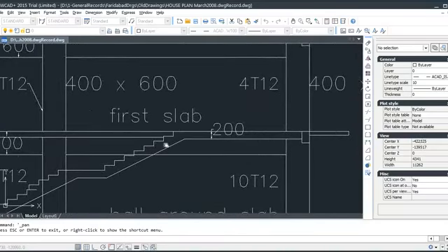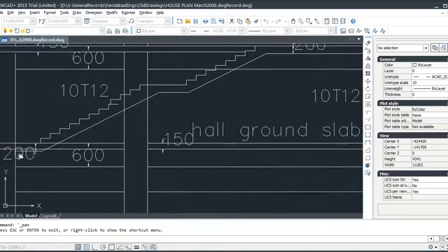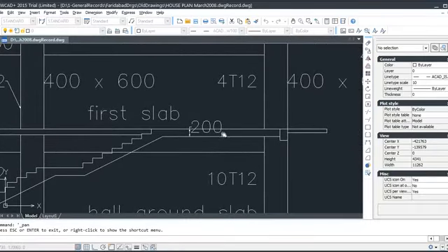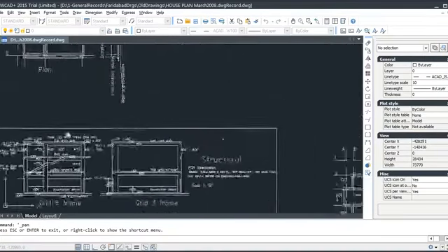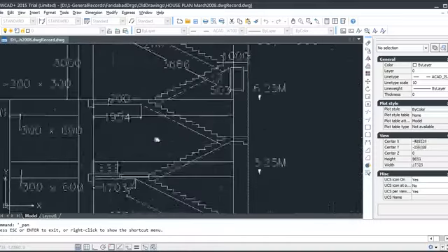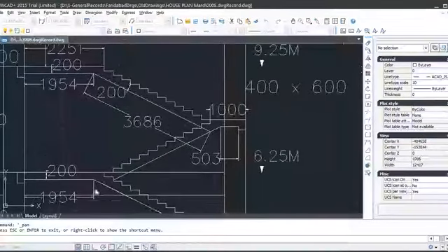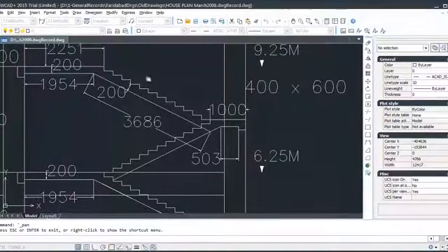And when we cast this portion, it is cast with upper slab, and this is cast after slab is done. So this is cast one landing, and this is cast in upper one. This is general practice, but nobody stops you if you take whole slab of stair, this one or other one, whatever you have. If you take whole this and that together, no bar. If you take separately, no harm. You have to leave dowels here.